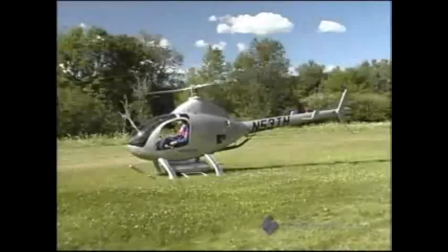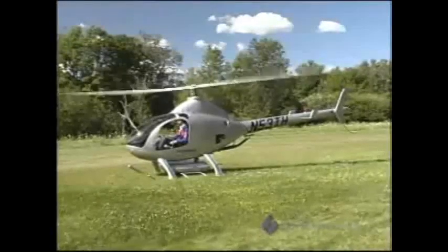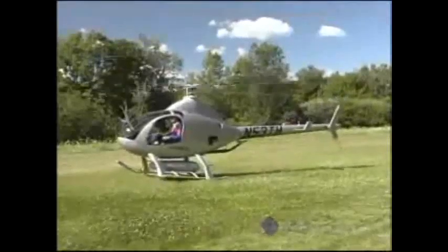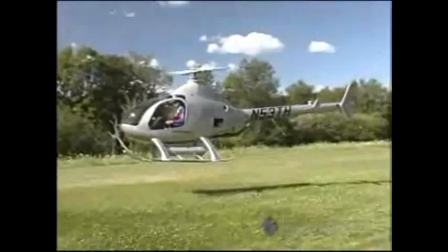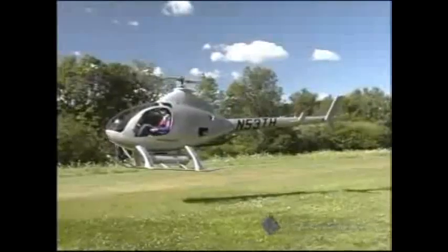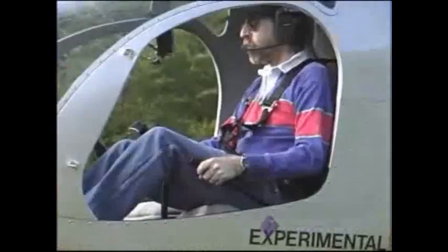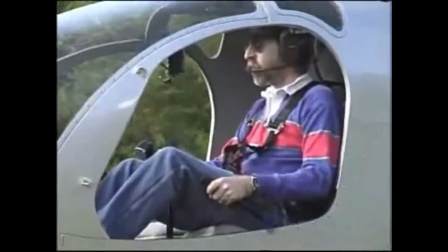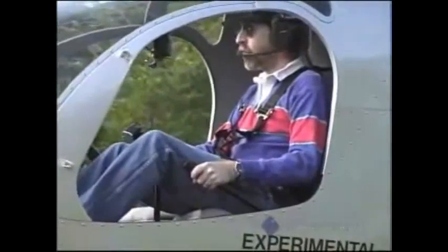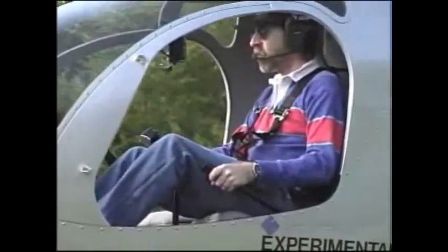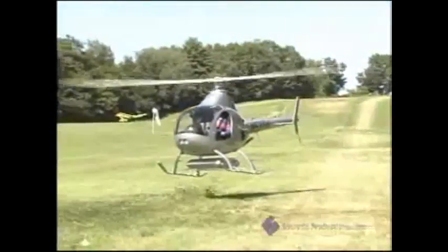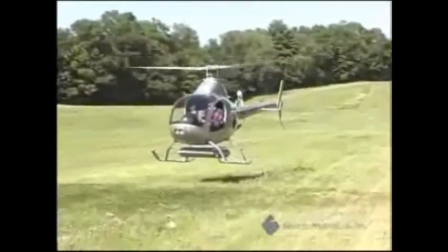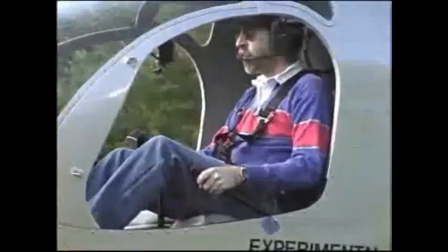With traditional fixed-wing aircraft, the faster it moves through the air, the more lift it produces. But a helicopter can fly without any forward movement at all. It can hover. Rather than moving the whole aircraft through the air to generate lift, helicopters use rotary wings. It is this ability to separate the aircraft movement from the generation of lift that allows a helicopter the advantages of vertical takeoff and landing.